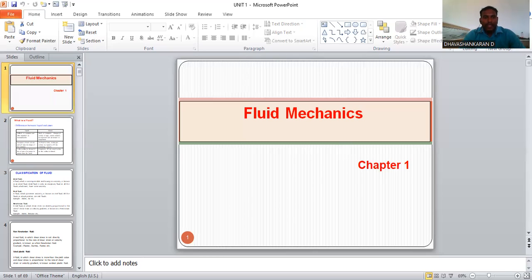Then specific gravity has the formula density of liquid divided by density of water. The density of the unknown liquid is 713.5, and the standard fluid density is 1000. Calculating this, we get the specific gravity as 0.7135. So we have arrived at all the data asked in the question. That's all about the properties of the fluid. Okay, thank you for the wonderful session.